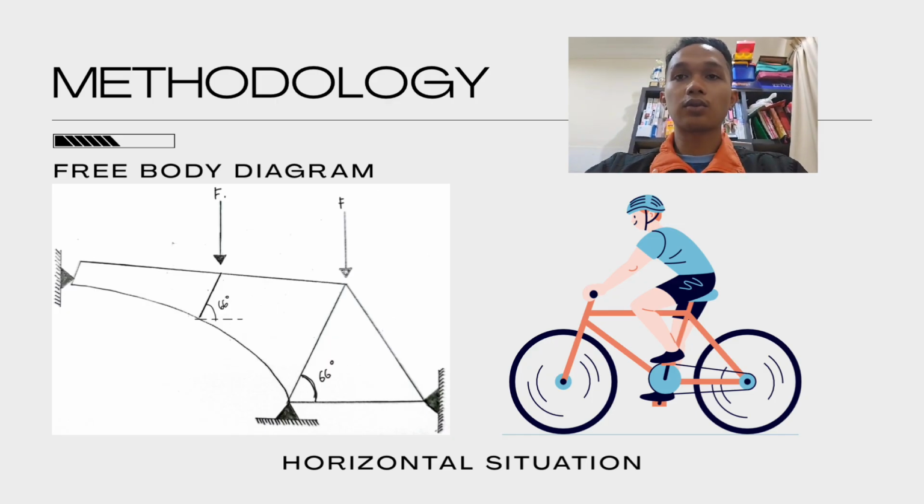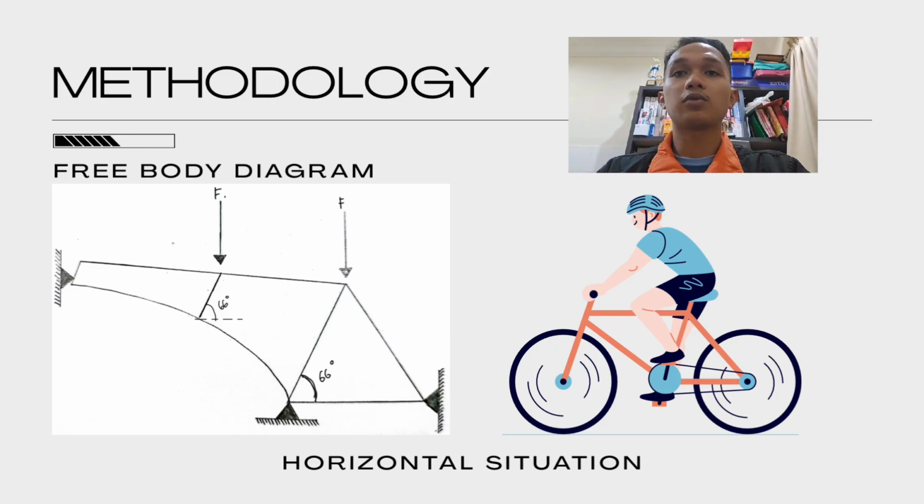Since there is no slope, no additional horizontal forces are acting, so the ground provides a reaction force upward, and also a horizontal reaction if necessary to prevent slipping. So the key points of this free body diagram on a flat surface are the vertical weight force, the fixed support providing vertical and horizontal reactions, and equilibrium in both the x and y directions.